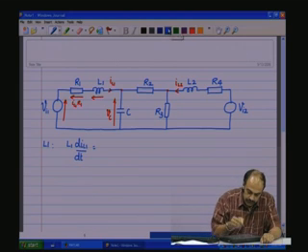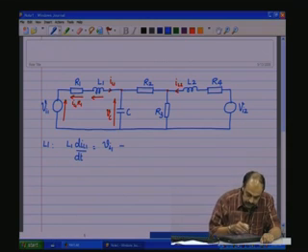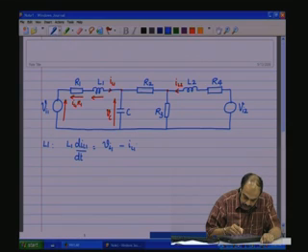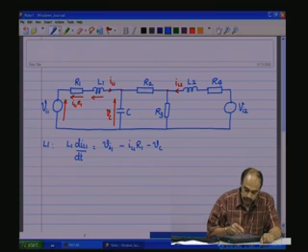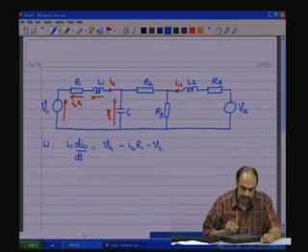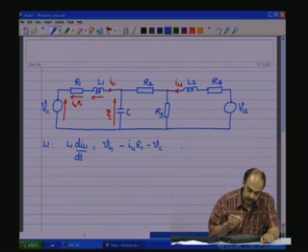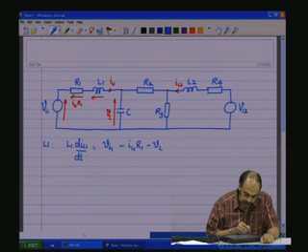So, now we have the equation which is very simple. We have VI1 minus IL1 R1 minus Vc should add up to the voltage across the inductor, such that the sum of the voltages, the algebraic sum of the voltages in this loop, in this voltage junction, is 0 by Kirchhoff's voltage law. So, this is our first equation, and now the second equation.